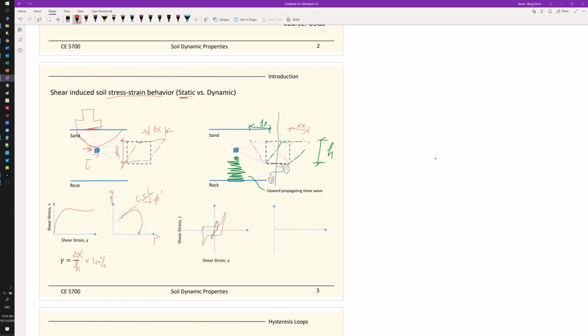So this is the stress path for static loading here, and for cyclic loading, again the same p-q plot, and now this will go back and forth. So this could be your first cycles, and then you keep loading it, and then realize this is the mean effective stress, right? P is equal to 1/3 of sigma V plus 2 times the horizontal stress.